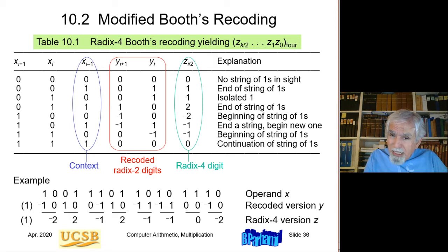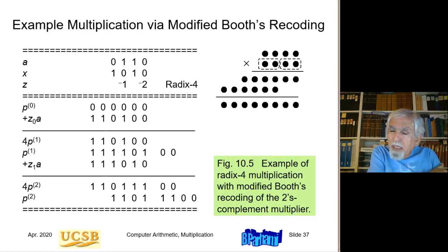I don't need to extend the number. So for 2's complement numbers, Booth's recoding directly gives me the correct value of the number, which happens to be negative here. So that's why here you see that 1010, a 2's complement number, which is negative, is correctly recoded as a negative number.